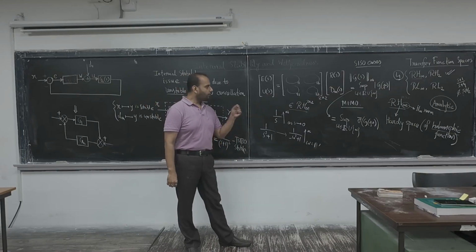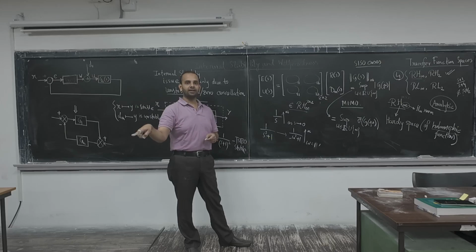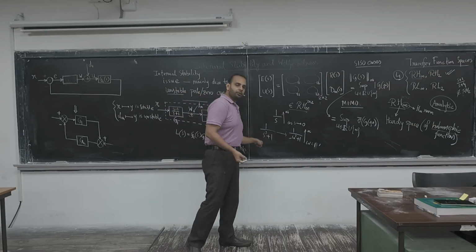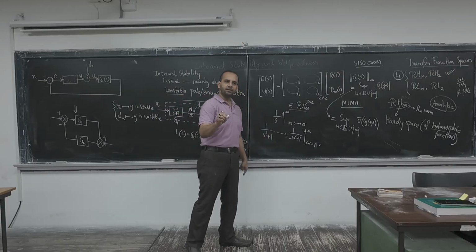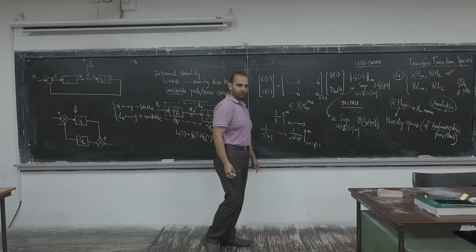And if you have understood the definition, then the reason is also clear why a transfer function having a pole on the j omega axis or on the open right hand side has an infinite H infinity norm. Because at that particular frequency, the denominator becomes 0, as a whole the function goes to infinity, that means the gain is infinity.